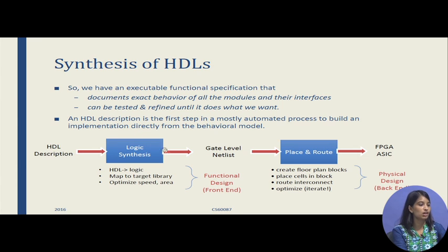So what I mean by logic synthesis is we have an HDL description of the system, we map it onto hardware like AND gates, OR gates, or counters, or some higher level ALUs, for example. So to get a netlist, we feed the HDL description and target libraries into the tool, which has the basic primitive logic gates and digital constructs, and which is technology specific.